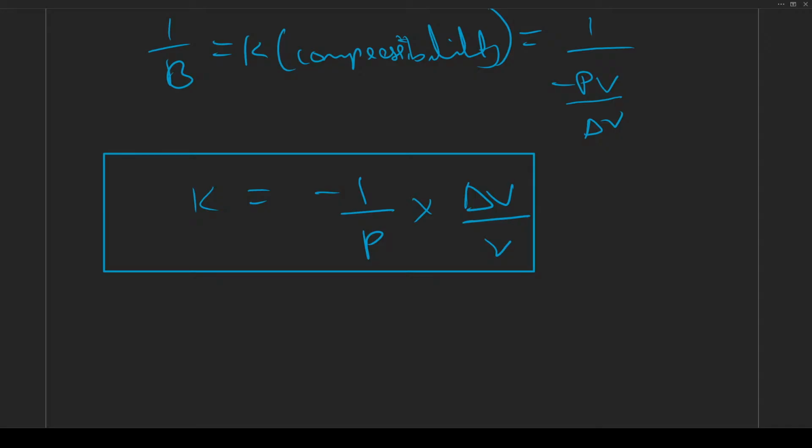The fractional change in dimension perpendicular to applied stress. When you stretch a body, interatomic forces try to maintain volume for most materials approximately. So as the body becomes longer, its cross-sectional area tends to shrink. This gives a negative lateral strain proportional to the positive longitudinal strain. The proportionality constant is Poisson's ratio, which is lateral strain by longitudinal strain. This negative sign ensures positivity of mu.